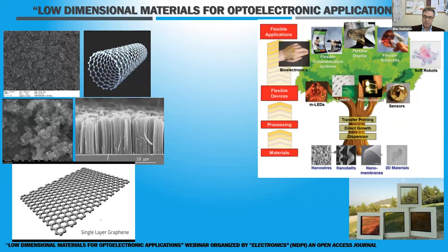In terms of dimensions, the 2D material is a layered structure and the movement of the particles is limited in one dimension. The atoms in the plane are bonded by covalent bonds and the layers are bonded by van der Waals forces. 2D materials achieve an ultra-thin thickness at the atomic level, which distinguishes them from ordinary conventional materials in dimension. Correspondingly, one-dimensional materials with 2D motion constraints and zero-dimensional materials with finite three-dimensional motion have also been extensively studied.